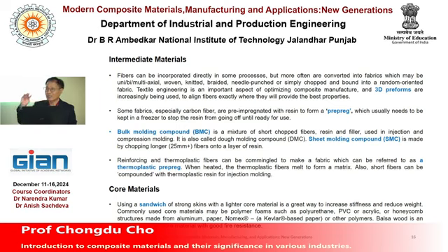Prepreg looks like a tape, just like 3M tape. It can be used as a raw material form to make specially shaped composite material. And the BMC terminology. BMC is a bulk molding compound. So this is a mixture of short chopped fiber, resin, and filler used in injection. So that is BMC, and also SMC. SMC is a sheet molding compound.